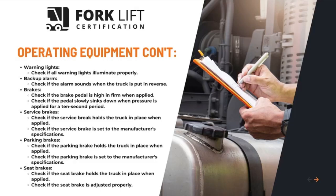Parking brakes. Check if the parking brake holds the truck in place when applied. Check if the parking brake is set to the manufacturer's specifications. Seat brakes. Check if the seat brake holds the truck in place when applied. Check if the seat brake is adjusted properly.